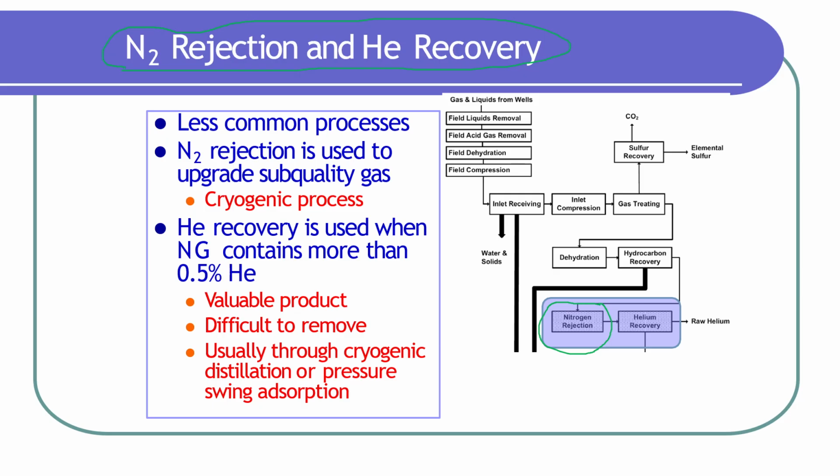For the helium recovery, which is not commonly used, it will normally be done if you have a helium content of 0.5%, and it can be done for many reasons. One of the main ones is the value of the helium, because as you know, helium is a very expensive component, and if you can recover it from the gas stream, although it is available at only 0.5%, given the fact that you are processing a very high quantity of gas every day, this means that you can recover a large quantity of helium per day. And given that it's very expensive, the process is feasible.